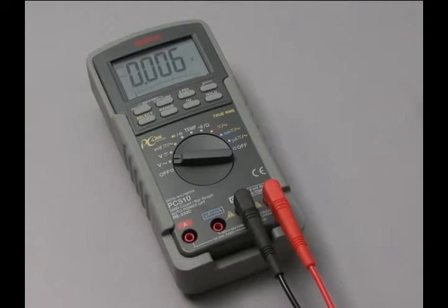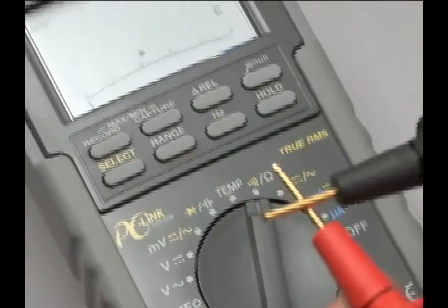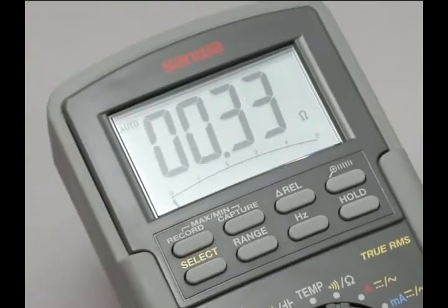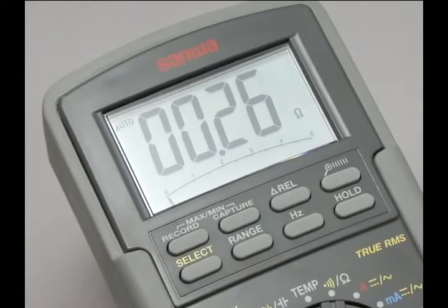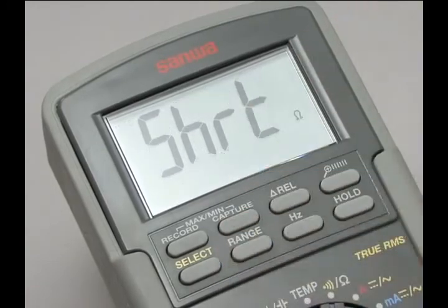The precautions adopted with the analog tester should also be adopted when using a digital tester. For example, the practice of making zero-level adjustments should be followed before starting measurements. Refer to the instruction manual, because methods for making zero-level adjustments vary according to the type of tester.